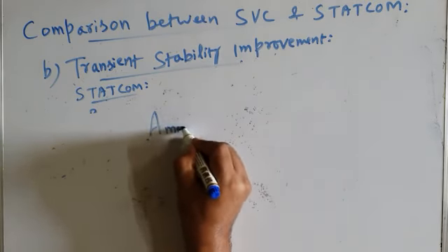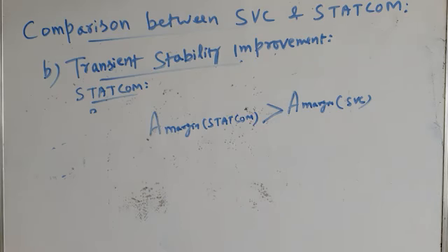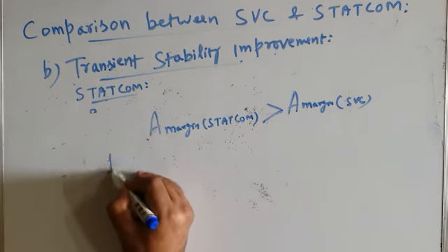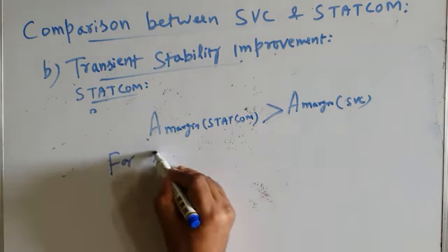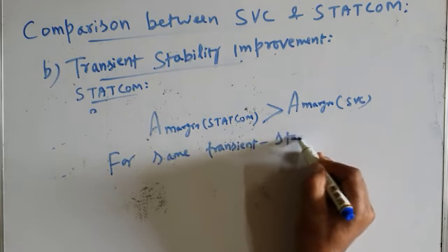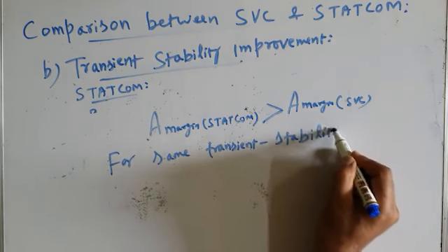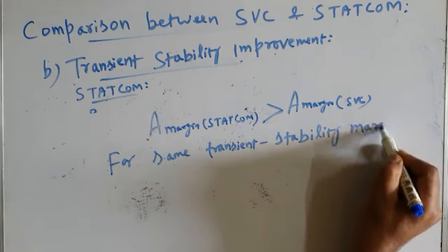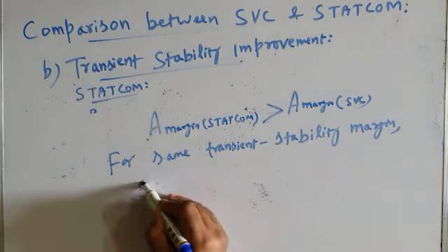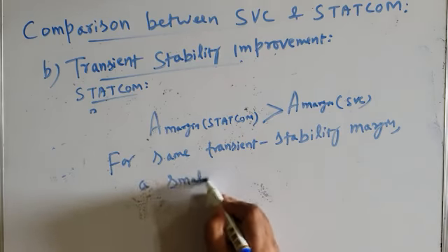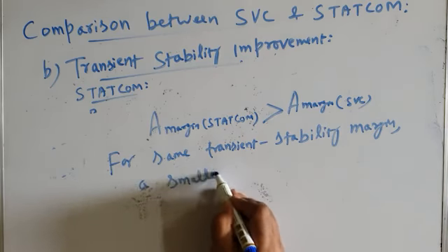So for the same transient stability margin, if the same transient stability margin is required, a smaller rating STATCOM is required.